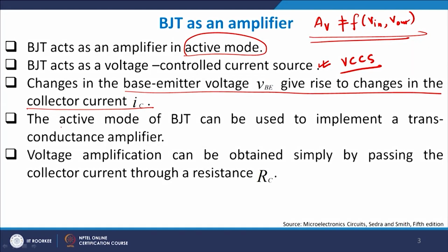If you are using a silicon transistor and your VBE is less than 0.7, you can be amply sure that the emitter base junction is cut off, and therefore no appreciable current is flowing through the emitter base junction. So, your device will be in the off state, because you are not allowing any of the majority current carriers, the electrons in the case of an NPN transistor, to flow.